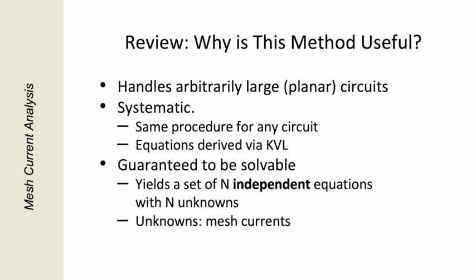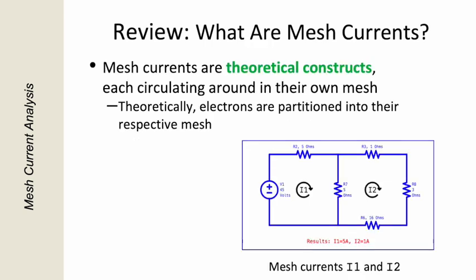Okay, so as a quick review, why is mesh analysis useful? Great technique, powerhouse technique, handles arbitrarily large circuits, albeit they need to be planar. It's systematic, use the same procedure for any circuit, and the equations that are derived are via Kirchhoff's voltage law, easy. Okay? Guaranteed to be solvable. Going to yield n independent equations with n unknowns. And our unknowns are these mesh currents.